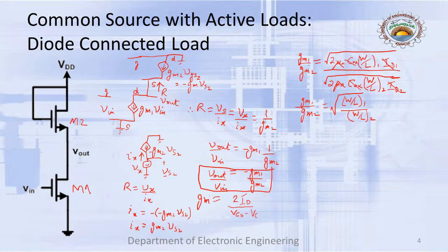If you see, it's actually a voltage dependent current source whose other end is grounded, and the magnitude of this source is, rather, minus gm2 VS2, because the gate is grounded as well. You can see it here. This is the gate which is grounded since it is connected to the drain. So it means that VGS2 would actually be minus VS2.